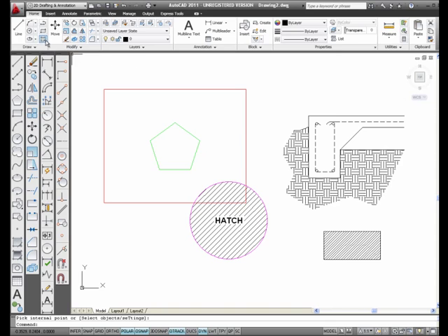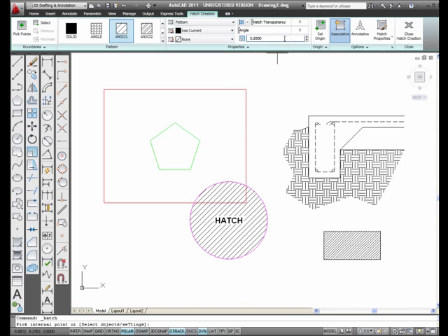Now what I'm going to do, hatch, I'm going to increase it, and I can do that by just picking here. And let me go ahead and go up to 2. Sweep across it, type in the number 2, and you got it. You can fool around with these and scroll up and down with these buttons, but sweep across it and type in what you want. I'm also going to change the angle.